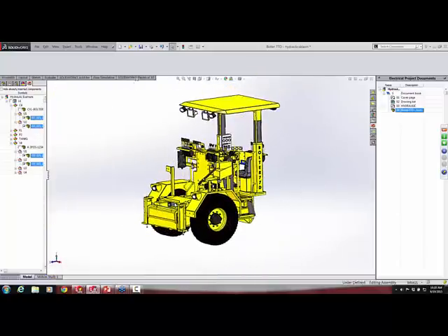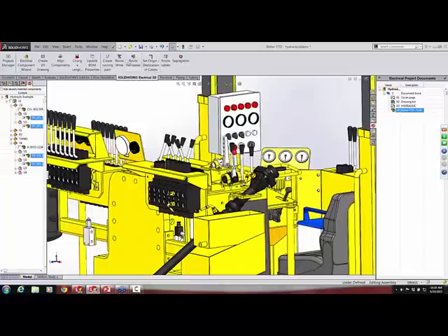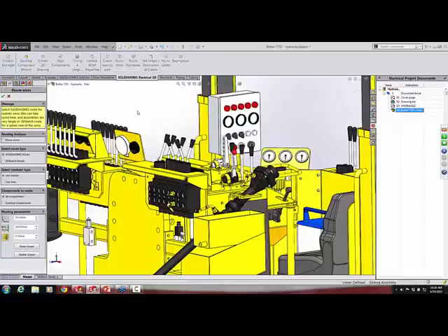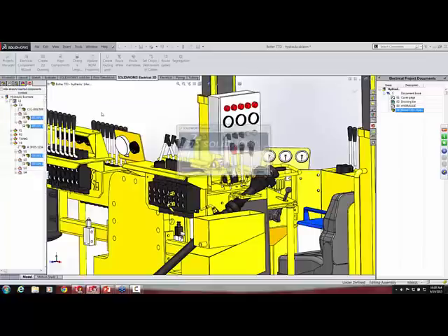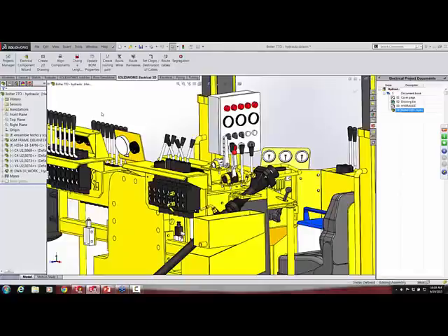So go to my command manager, the electrical 3D side of things, and to route the hose, I can just route wires because it's thinking that these hoses are wires, so just route wires. Use the SolidWorks route. I could route it with just 3D sketches. I want to use a spline, and just OK that. And what it's doing, it's basically creating a from-to list from the 2D schematics. And it's going to route the hoses where they're supposed to be.